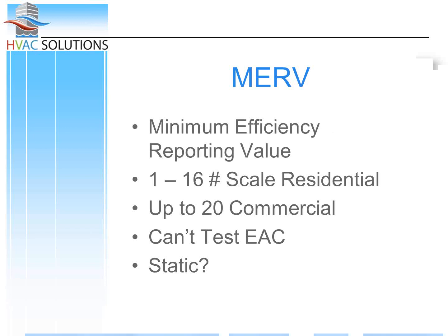Okay, so here's a table that shows what MERV actually means. This is a residential table. See, we stop at 16. Commercial would expand beyond that. Most standard media filters are going to be in that 8 to 13 MERV rating range.